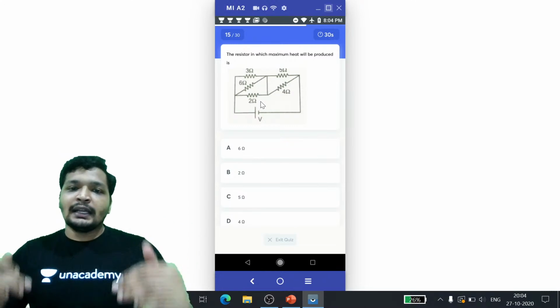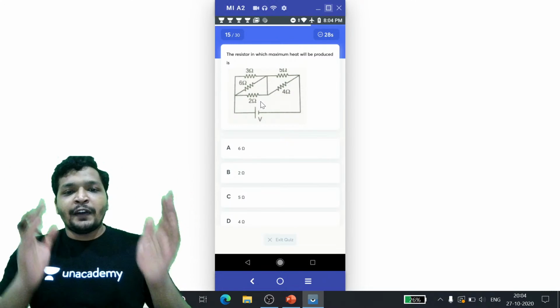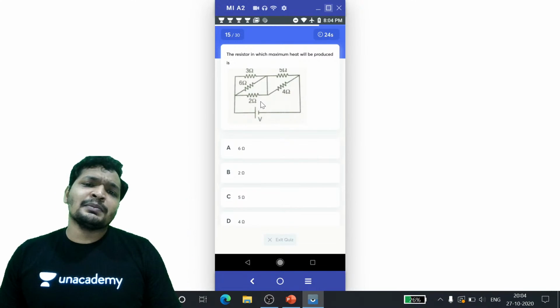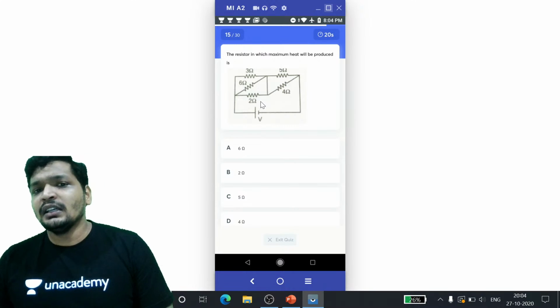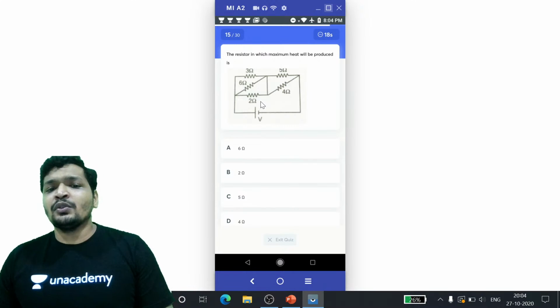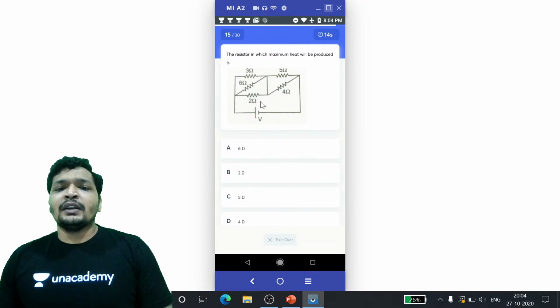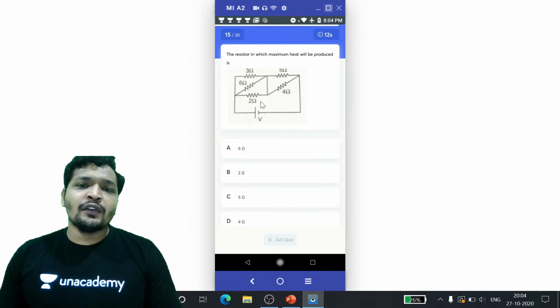Because here again 3, here again 2, you need to find out how much is the equivalent resistance. But I guess 1 by 6 plus 1 by 3 isn't that easy? Yes, that is a little bit easy. So that would be 2 ohms. Again 2 ohms, that is going to be 1 ohm. If this is 1 ohm, you can find out the equivalent of this.